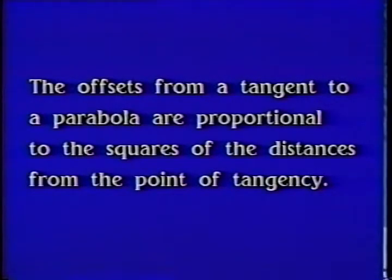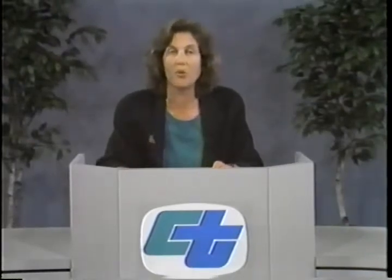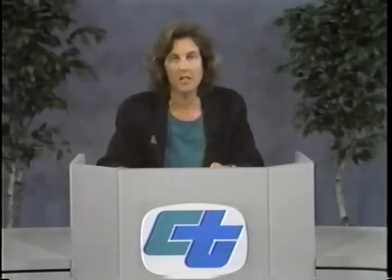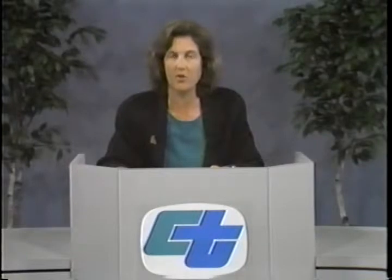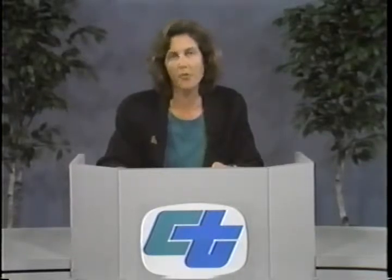The offsets from a tangent to a parabola are proportional to the squares of the distances from the point of tangency. This presentation will only discuss the parabolic curve equation. It is less complex and well suited to computer and calculator use. Other curve computation methods are no less correct, and some familiarity with them is encouraged. Most of the sources listed in the workbook cover both methods.